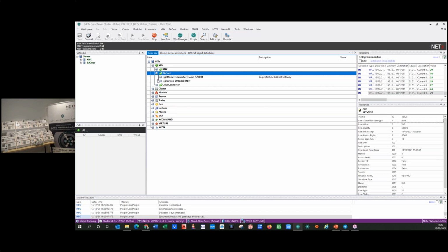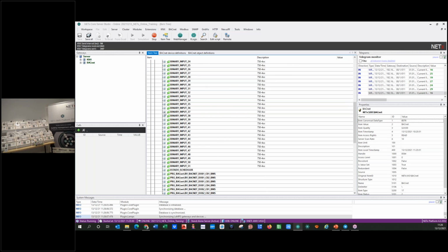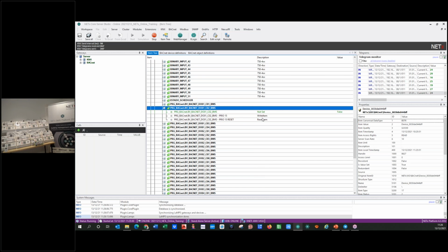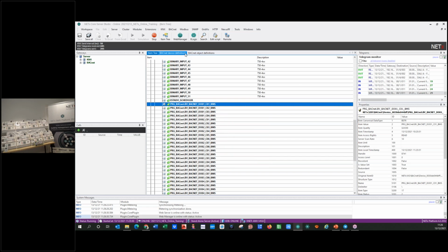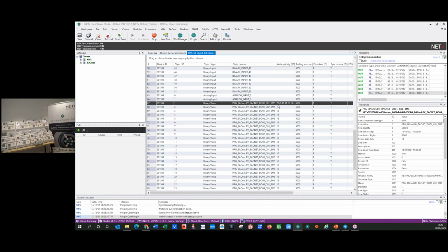this. In BACnet, for example, I will show you the second is as usual for the last priority number 15, but look at the first one. You have all the possibilities to check with the right item for the priority number 7, 8, whatever. And this is just a very easy change you need to do in the BACnet object definitions table. I will put them back again to 15 and in the next.